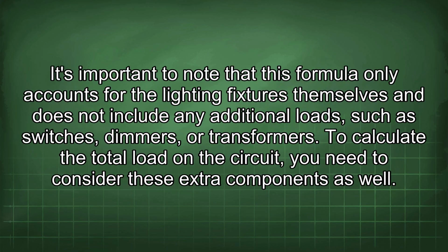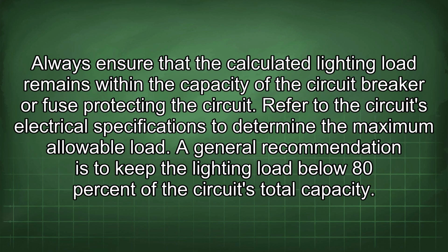It's important to note that this formula only accounts for the lighting fixtures themselves and does not include any additional loads such as switches, dimmers, or transformers. To calculate the total load on a circuit, you need to consider these extra components as well. Always ensure that the calculated lighting load remains within the capacity of the circuit breaker or fuse protecting the circuit. Refer to the circuit's electrical specifications to determine the maximum allowable load.